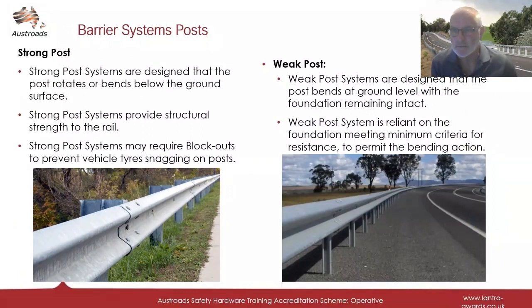Strong post systems. Strong post systems are designed so that the post rotates or bends below the ground surface. Strong post systems provide structural strength to the rail. Strong post systems may require blockouts to prevent vehicle tyres snagging on posts.